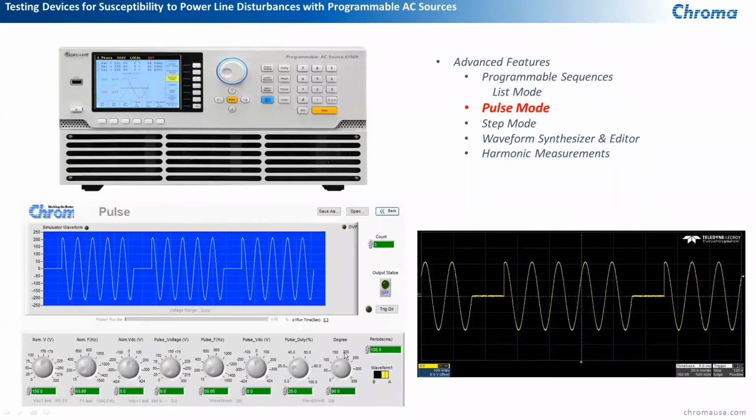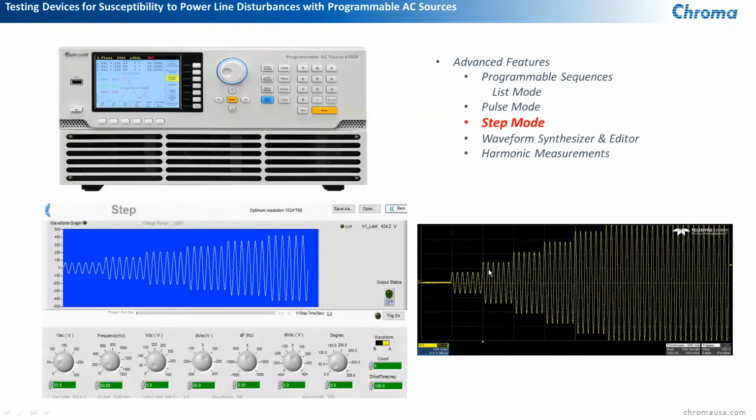It gives you the phase angle degree where you're going to start the pulse at. If it's going to be at 90, 0, 180, you can set it in 0.1 degree increments. You can set the period of time, so you can inject it, and then you would have a total time where it would go back to normal operation.